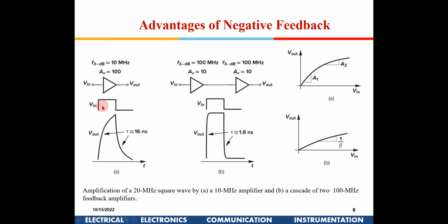Small signals don't change your operating point, but such large signals will change the DC operating point of the amplifier. So there is a possibility that transistors will come out of saturation. It is very difficult to design an amplifier for a large input common mode range. Since the operating point itself is changing, the gain cannot be constant.